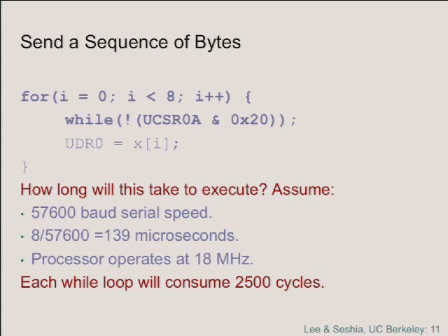What do you think is the data that's going to go out on that serial port? It's going to be garbage, right? It's possible that one bit will get out, and then the interrupt service routine will try to send out 8 bytes, right? Maybe one bit will get out of what it sends, and then you return from interrupt, and this guy overwrites the register and stomps over the rest of the 7 bits of the word that get sent out, right? And what ends up getting sent out is garbage. You have to not let that happen, right?